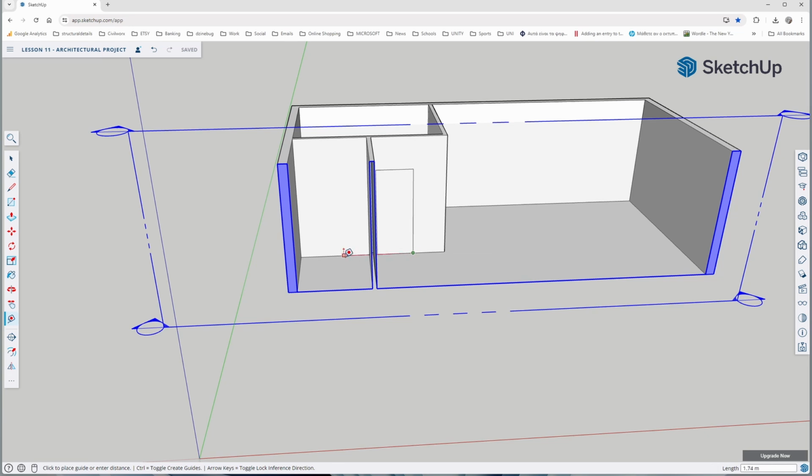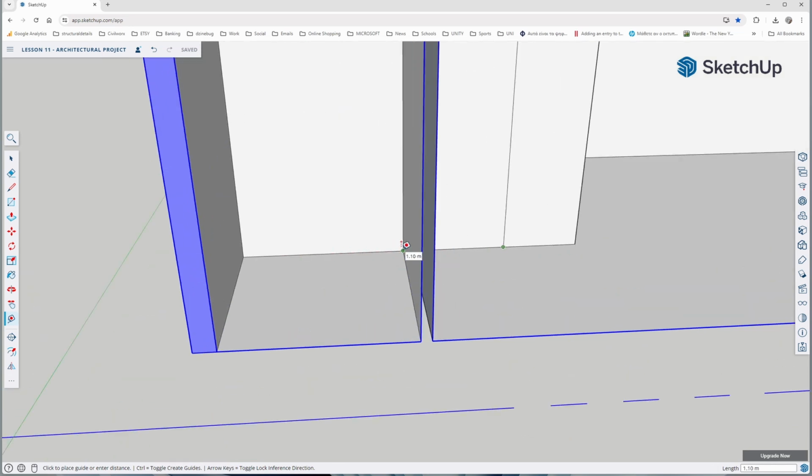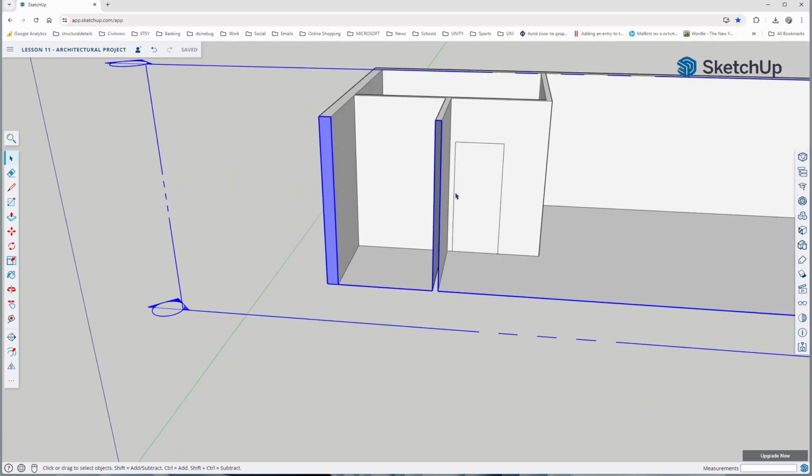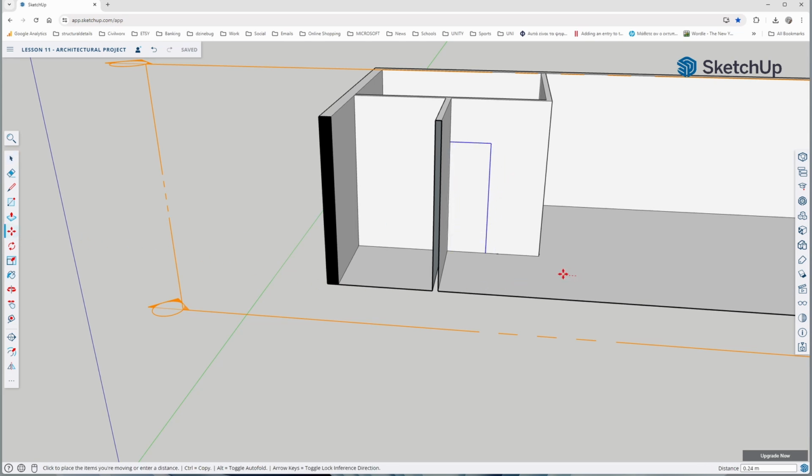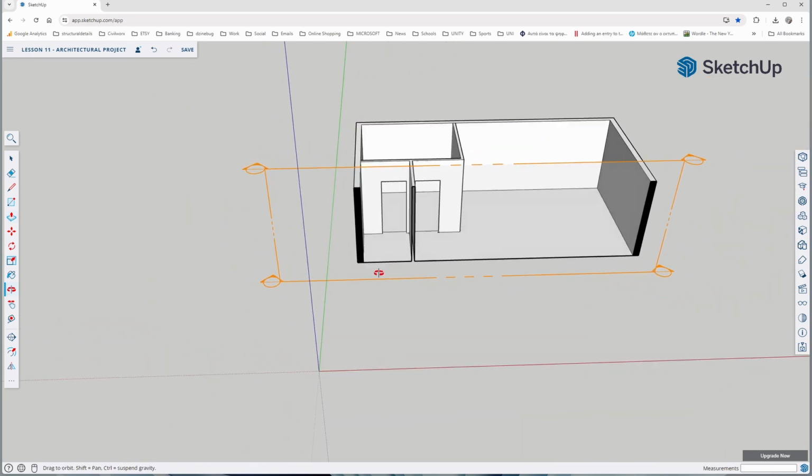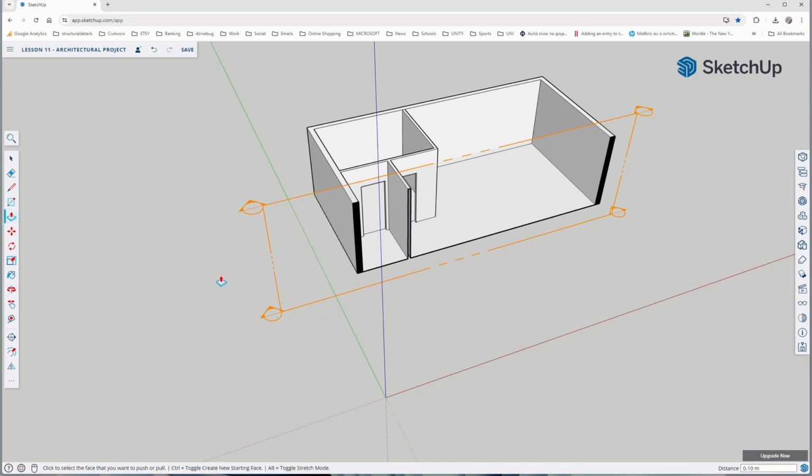I want to move it by a distance of 1.2 meters. So select the three lines, holding down the control key, select, move, control key to create a copy, 1.2. And now with the push-pull command, we will push these faces out, and it created a void, and again there. So now we've just opened two voids for two of our interior doors.